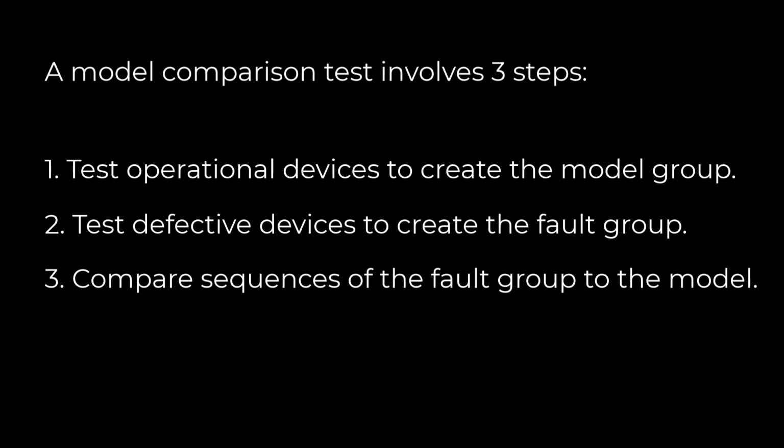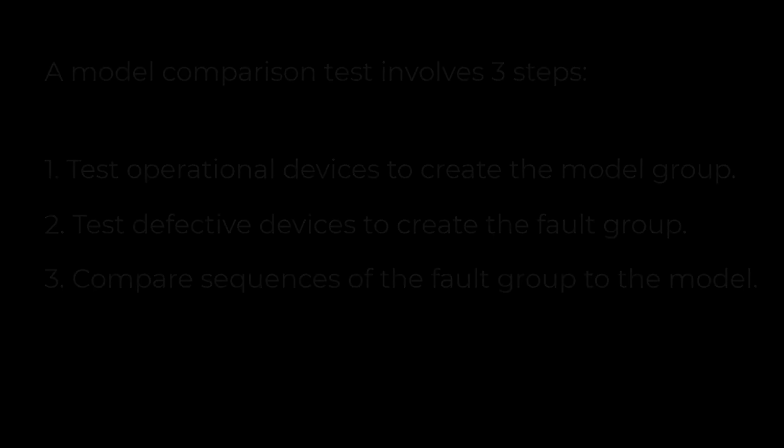Each test employs image subtraction, wherein a reference image of the unpowered device is recorded and then subtracted from each image that is captured while the device is powered. For step 3, each differential image from a defective device sequence is then compared to those of the model sequence.